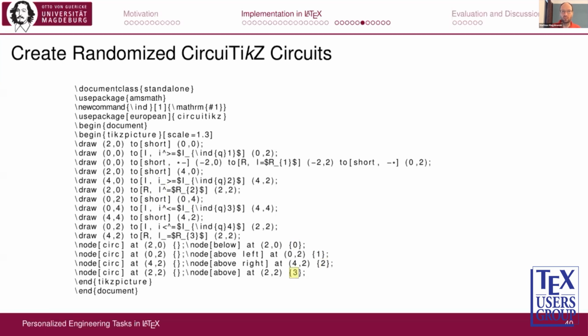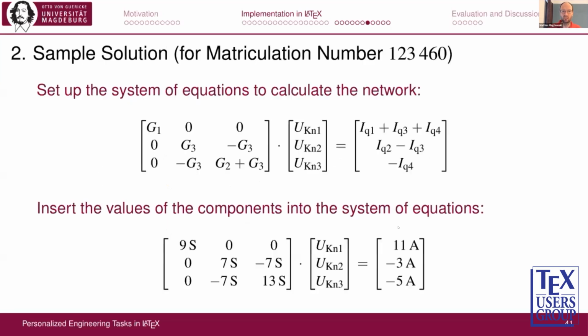And then from MATLAB I can not only generate the LaTeX code, but of course also run pdfLaTeX from a command line and generate the corresponding PDF files. And then a sample solution. Here I've displayed the system of equations that the students should set up to calculate the network. And there are the conductances of the resistors, these nodal voltages, and the current sources that are connected to a certain node.